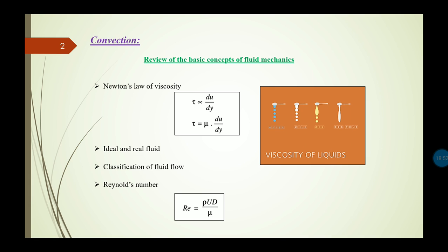Next, from 3.2 times 10 to the power 5 up to 5 times 10 to the power 5, the fluid flow is unpredictable, the transition zone. And when the Reynolds number is greater than 5 times 10 to the power 5, in case of a flat surface, the fluid flow is of turbulent nature. All these things regarding the boundary layer theory concept will be discussed in detail in the next lecture.